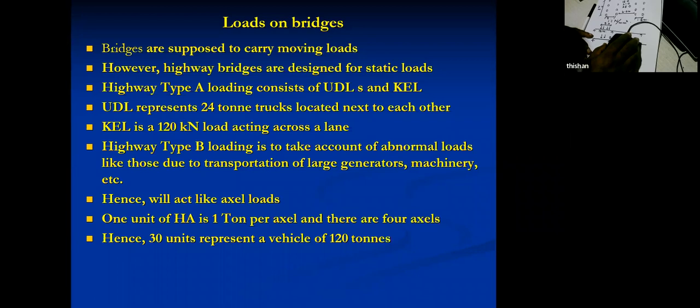Because they have more axles, again, the impact of such vehicles will not be that significant. A shorter vehicle with a heavy load can be much more significant than a longer vehicle with a heavy load, because the longer vehicle can have so many additional axles.